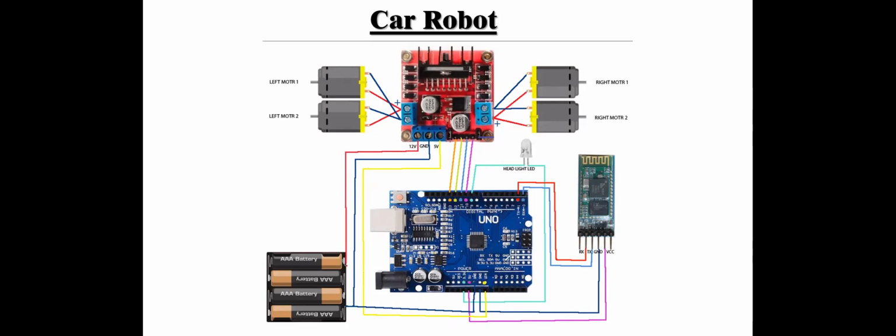That's up. Now we have to set up this one, right? So it is simple. In VCC, you can obtain 5 volts from this pink color one in the Arduino Uno, and connect it to the VCC terminal. On the ground terminal, you have to ground it. Simply, you can ground it to the Arduino.